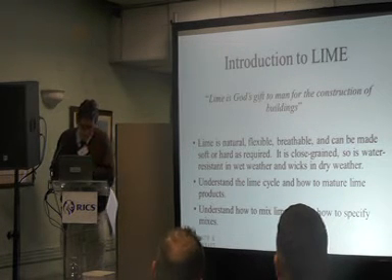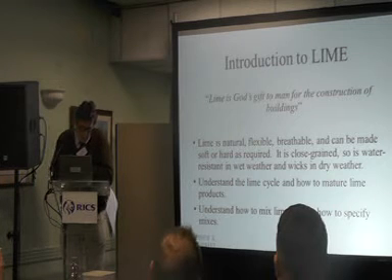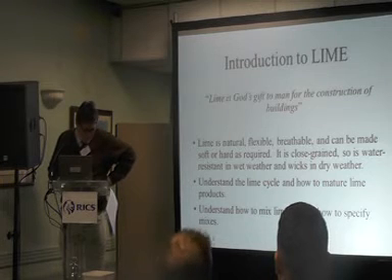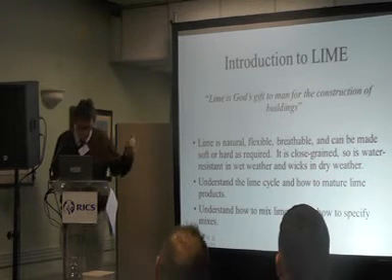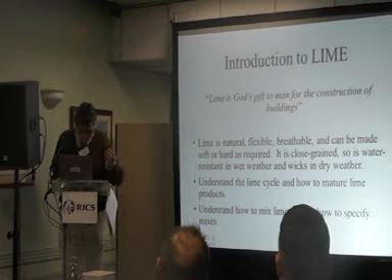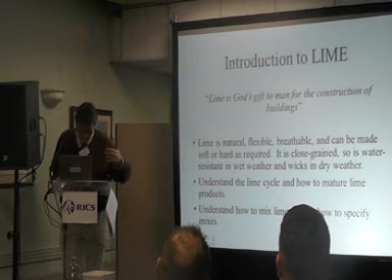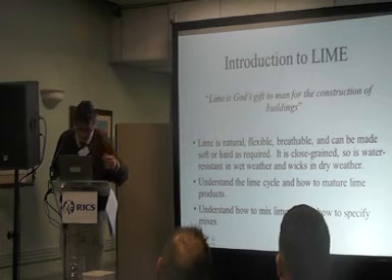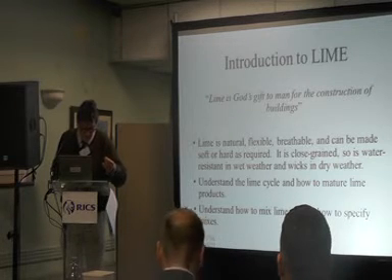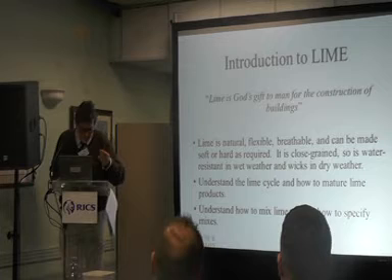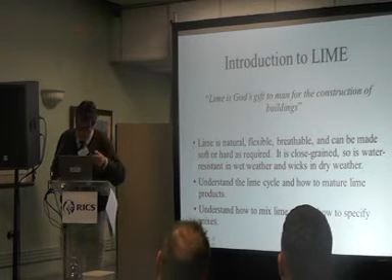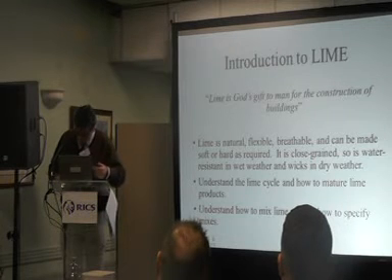Lime is God's gift to man for the construction of buildings. I don't know where I found that quote, but if it's not already attributed to anyone, I'm going to take it for myself. Lime is natural, flexible, breathable, can be made as soft or hard as you need to. It's close-grained, so it's water resistant when the rain's pouring on it, and it wicks in dry weather. In order to use it effectively, you really only need to understand two things: the lime cycle and how to mature lime products, and how to mix lime and therefore how to specify it.